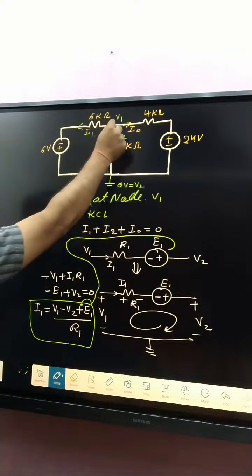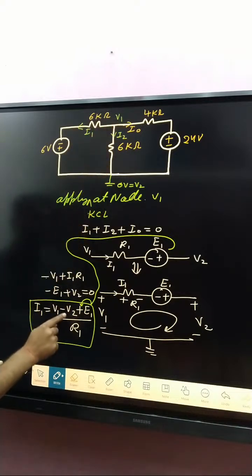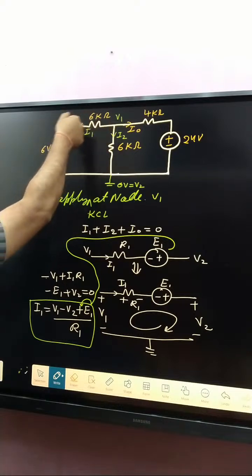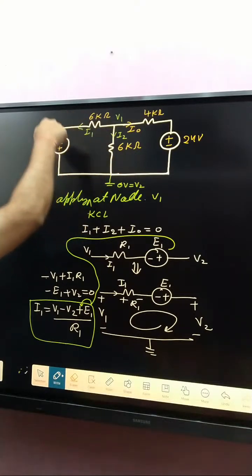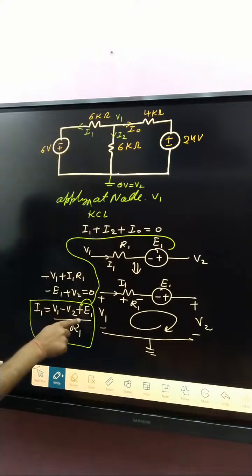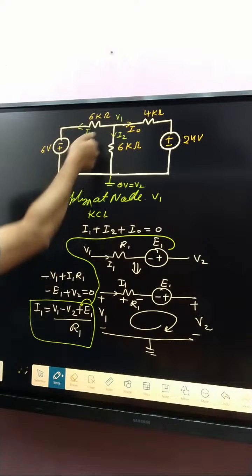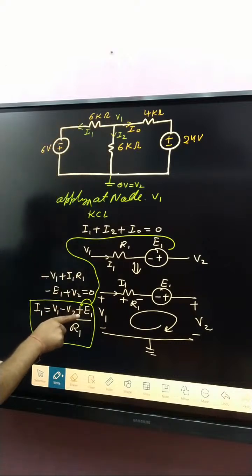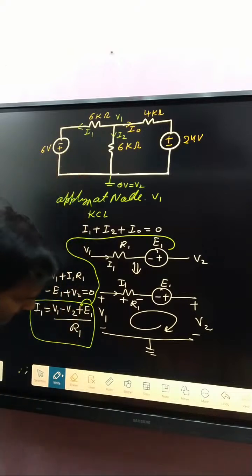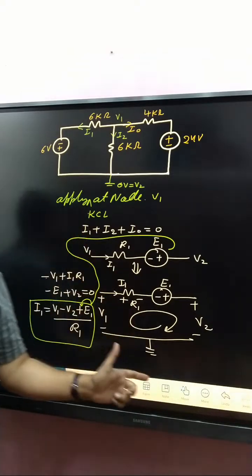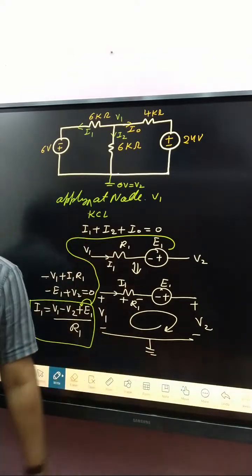Simply, initial voltage minus final voltage. If a voltage source is connected in the circuit and the current leaves from the positive terminal, then that voltage is written positive. If the current leaves from the negative terminal, then it is written negative. Clear or not? How can I apply that formula here? If anyone phased out, tell me, I will explain that concept again.